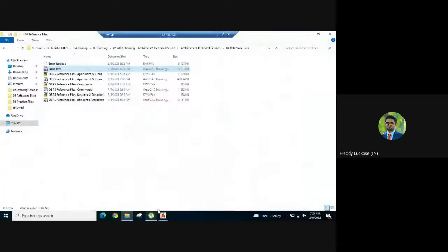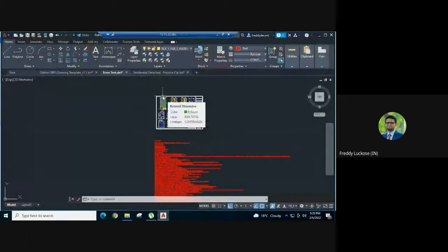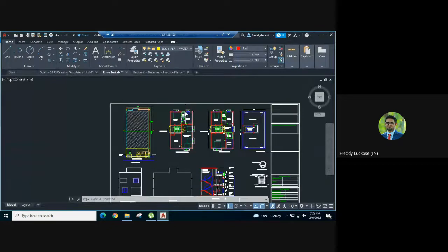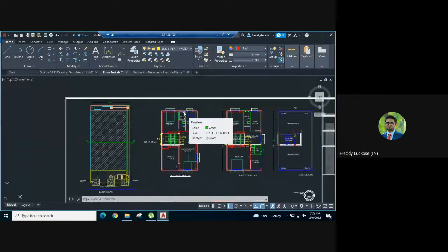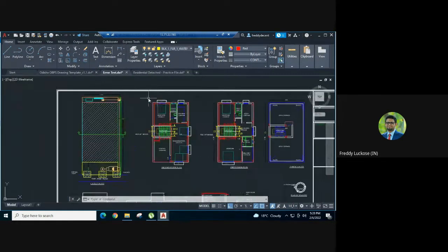So to summarize the entire thing that we were doing, these were the 3-4 common issues that come up in drawing. One is the layer name or the color code. Just check whenever that issue is coming regarding the 4 statements that you see. Just check for the built up area, plot boundary, building footprint, and plan info.